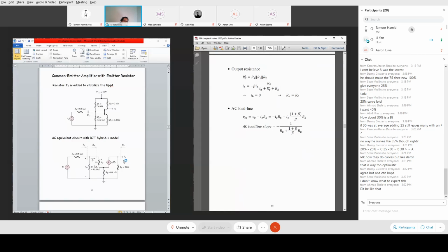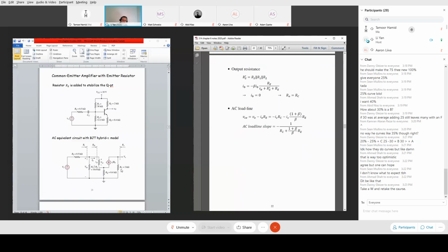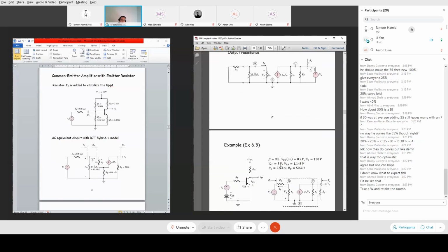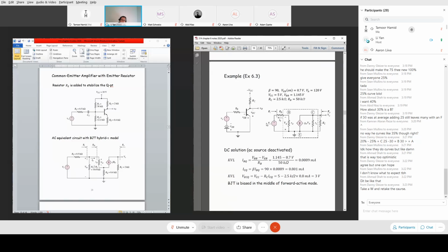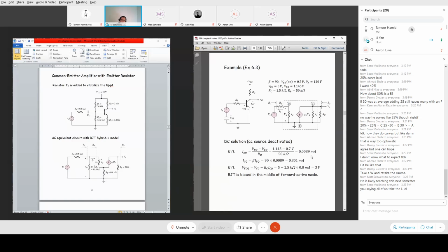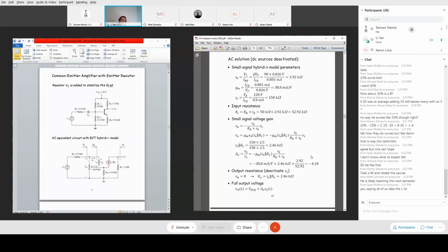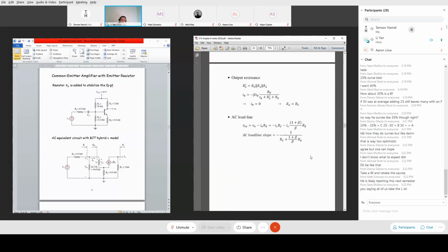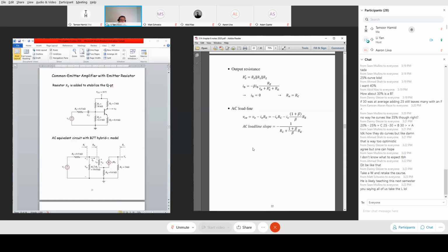Once current IB is 0, this dependent current source is a break, open, and then the output resistance seen from here is RC. So this RO equals RC. Okay? This is a big extension from the previous circuit. The previous circuit said we know the equivalent resistance is this guy. Then we say if I deactivate this S, there's no current here; that's what we concluded. But here, even with the emitter resistance RE, we still conclude the base current is 0. But you have to go through an even more convincing step-by-step derivation to convince me that indeed this is the case.